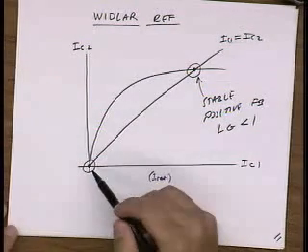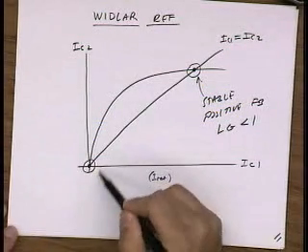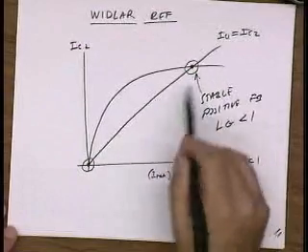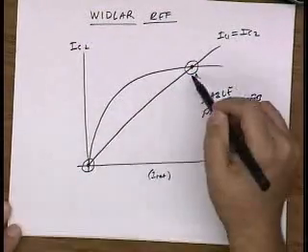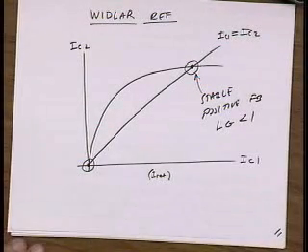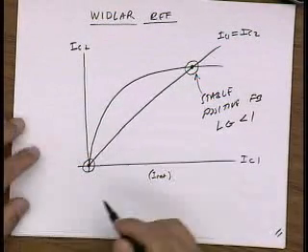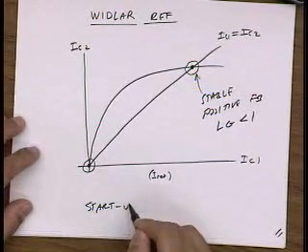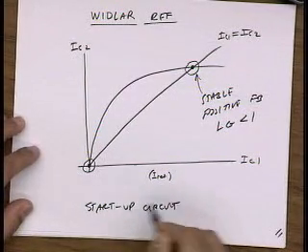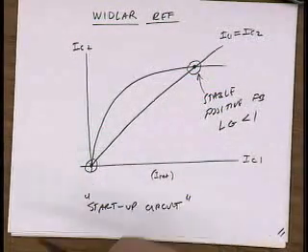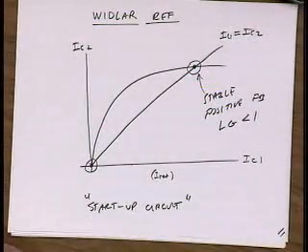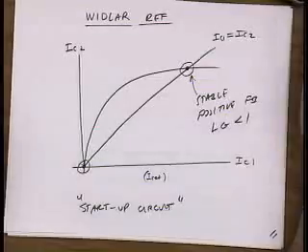So in fact, what we need to do is guarantee that we never end up in this dead state, that we always turn ourselves on. So we need a circuit that forces us into this condition. And it's actually very easy to design these so-called startup circuits. All the startup circuit needs to do is detect a zero current state and then force some current through the transistors, enough current so that it has enough loop gain to get into the right state. Okay. Questions?